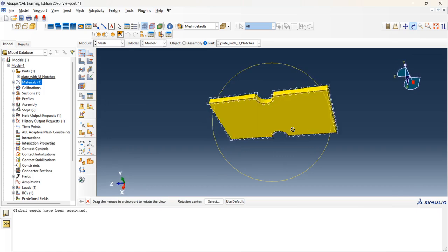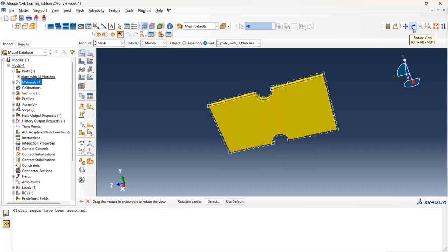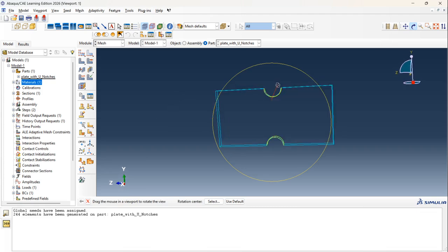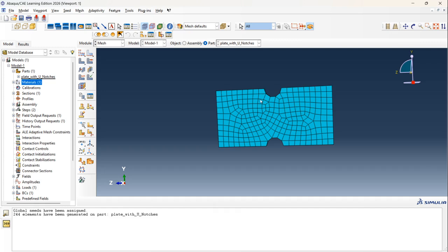Let's go for this first and see. So we will compare with the analytical solution. With the analytical solution, we can see if we need to adjust the mesh or not, because we can refine in this area. In order to have accurate results, when you have these notches here, you need to refine in order to have those accurate results. But let's go on job directly.